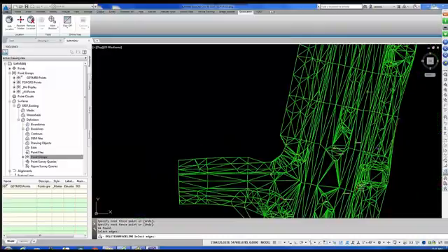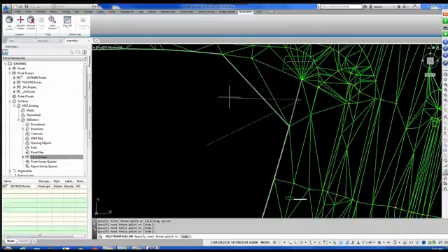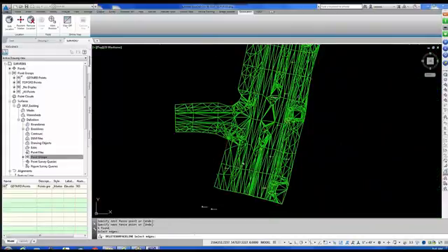All right, I'm going to zoom over to here, hit F for fence again, and I'm going to come in and do a little cleanup here. Okay. And again, what's happening is that sometimes the software tries to triangulate across these corners and these areas that I don't want to triangulate on. Now, I'm going to hit Enter, all right, and everything looks good.